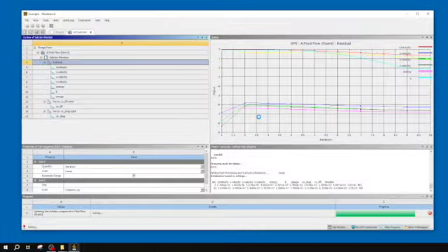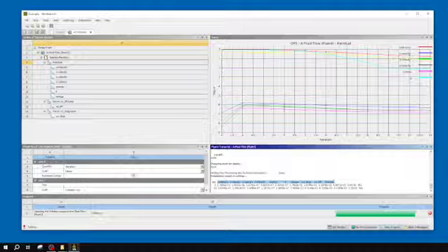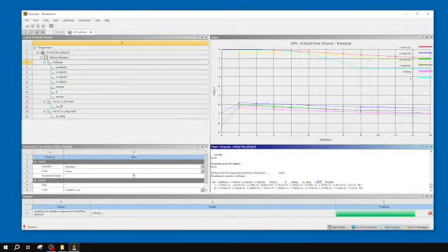Looking down at this output here, we'll see it displays a bunch of different parameters. We have what iteration it's on, all the different things it's plotting above in the residuals, but it also spits out my coefficient of lift and coefficient of drag. Those are these last couple numbers, so this would be my coefficient of lift right now, and this would be my coefficient of drag right now.